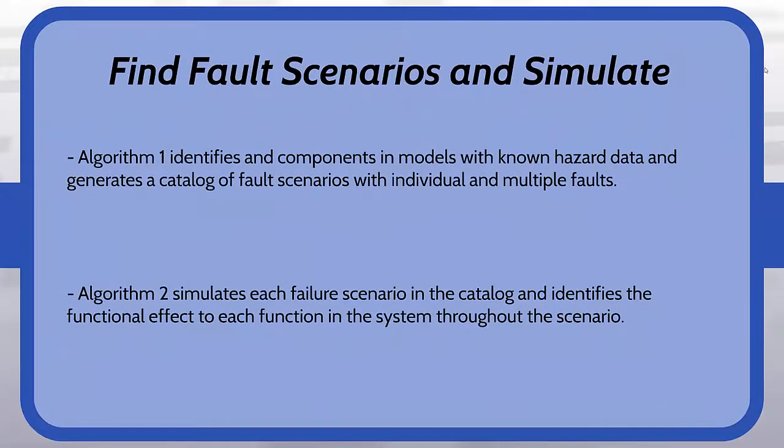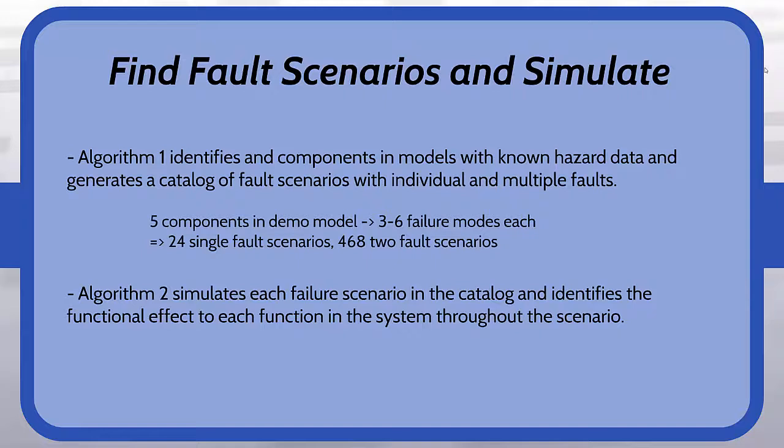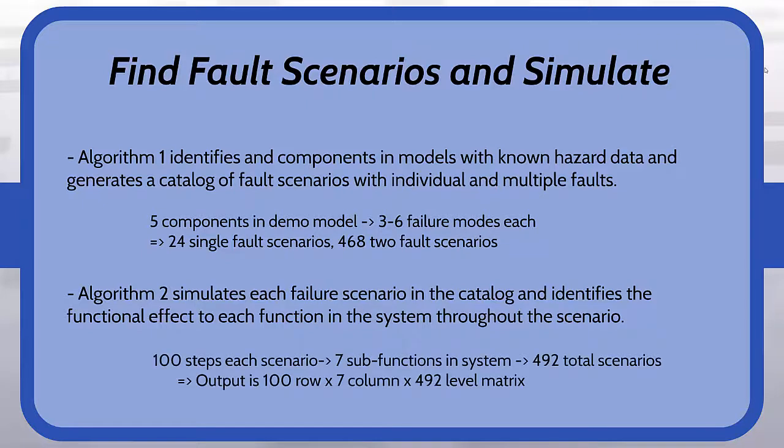We developed a few algorithms to search through the historic hazard data and build a set of testable failure scenarios, including single and multiple faults. For example, our system with 5 components, with 3 to 6 failure modes in each component, results in a total of 492 unique single and 2 fault scenarios. Additionally, we created an algorithm to automatically simulate those scenarios and collect the state of each function through each scenario. This forms the results that our reasoning methods will be exploring.